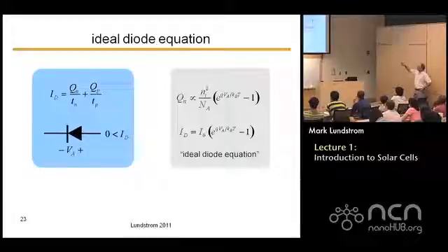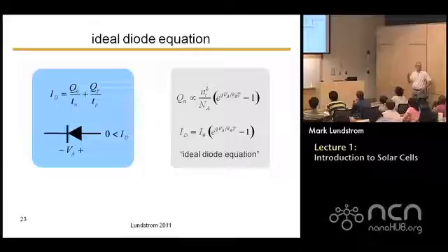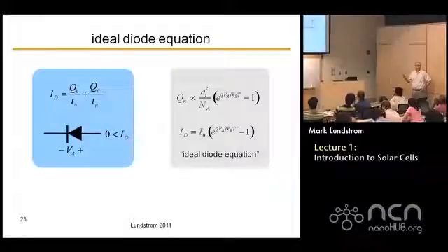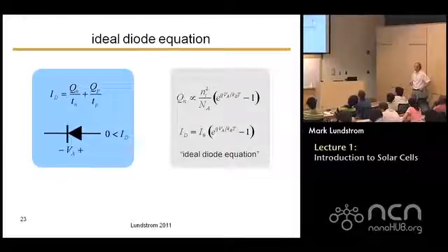Okay. So the charge is going to be exponentially proportional to e^(qV/kT). In equilibrium, we have the relation np = n_i squared. The equilibrium charge of electrons on the P side was n_i squared over the P-type dopant concentration. When I lower the barrier, I increase that by e^(qV_A/kT). The -1 is so that when I'm in equilibrium, I don't have any excess charge. Q is only the extra charge, not the equilibrium charge.